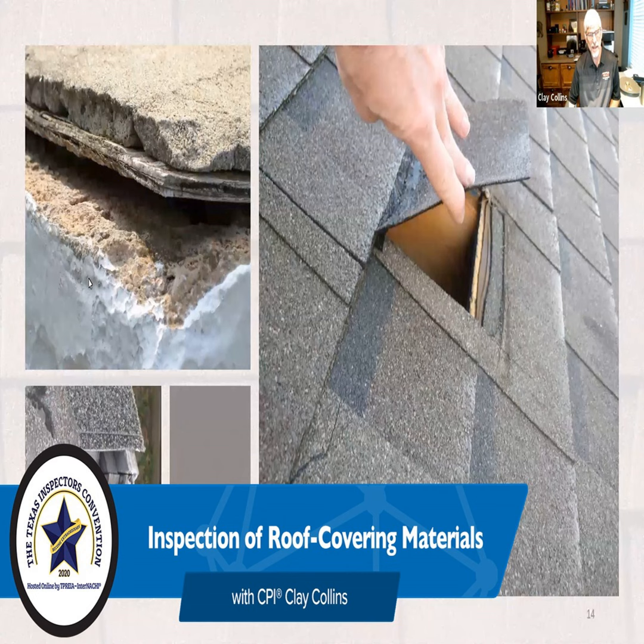And this is a case where the underwriter came in following a windstorm and said, we got all these problems. And if you look, you'll see that right here it was creased. It was creased. And all of these were lifted up. That's just because the front didn't adhere. So what happens? Well, you can have a real problem there. It just will allow those shingles to lift, and that will mean that you're going to lose some shingles. Or it might mean that you lose a lot of shingles.